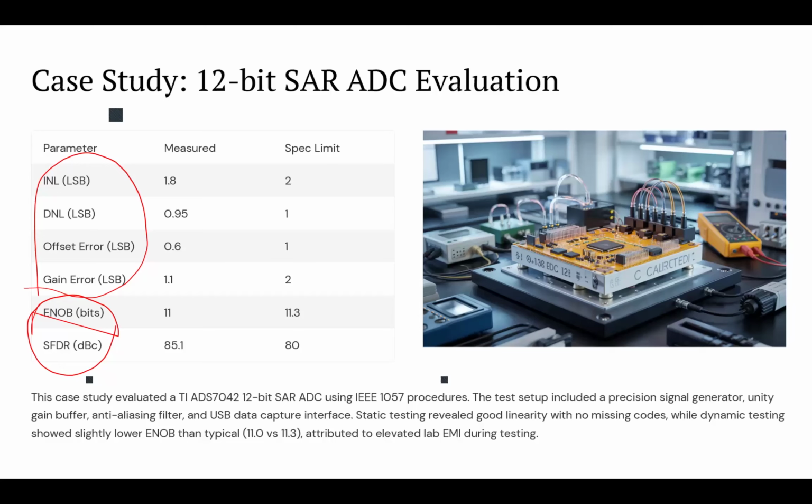Now, what about the dynamic testing? For dynamic testing, we said we need to apply a pure sine wave or a coherent sine wave to the input. Then we run an FFT on the output and we measure the parameters that we need to pay attention to and that are important for us.